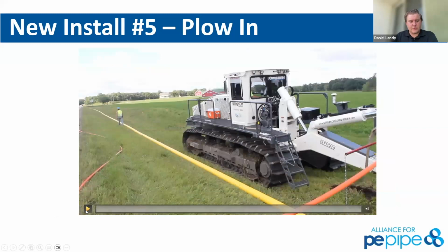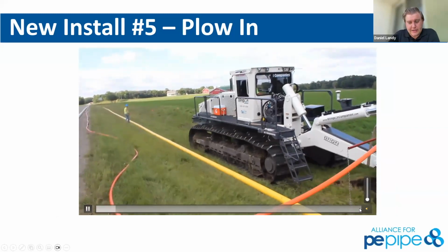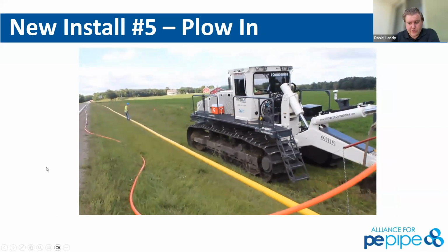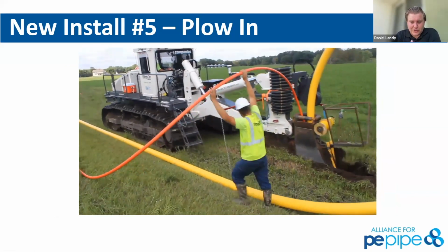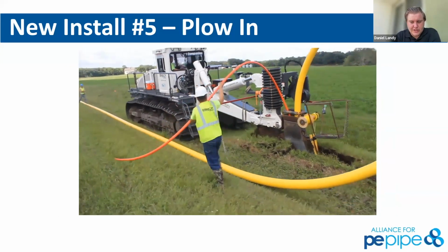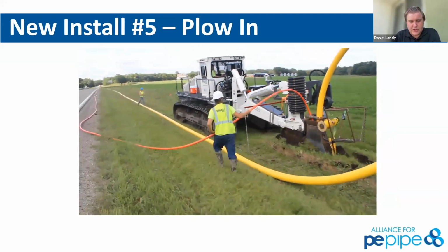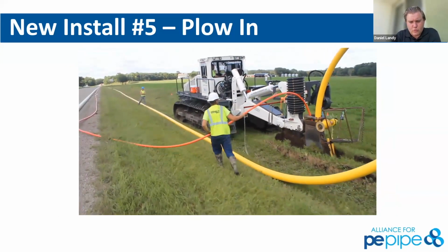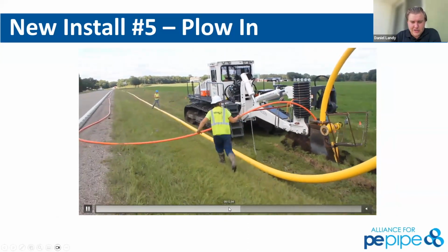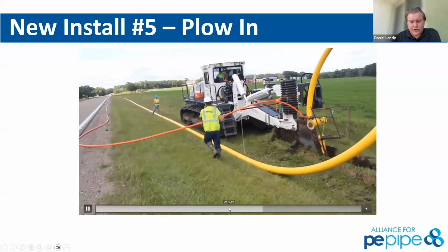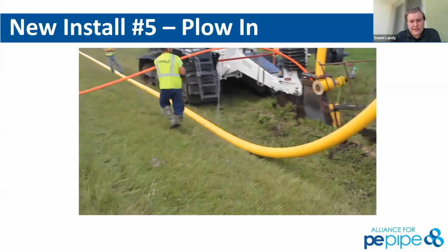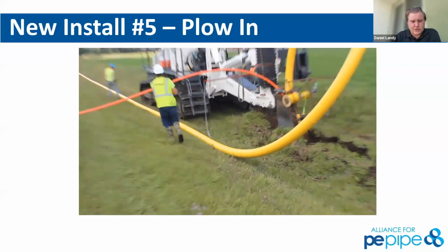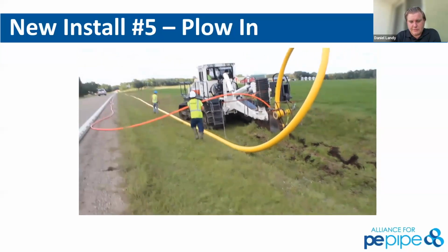Okay. Yeah, so the next one, this shows they're drilling in gas, oil. There are four different things: gas, electric, or a type of conduit, and then a caution tape, so when they're drilling, they know what's coming, and then a tracer wire. So four different things going into the ground at once. Once again, this is great for rural applications. This is a dumb technology, so it's not going to be sensing any other crossing utilities. That's why we mentioned that with those rural applications, they pretty much know if there are existing utilities or not, and they can avoid them if need be.